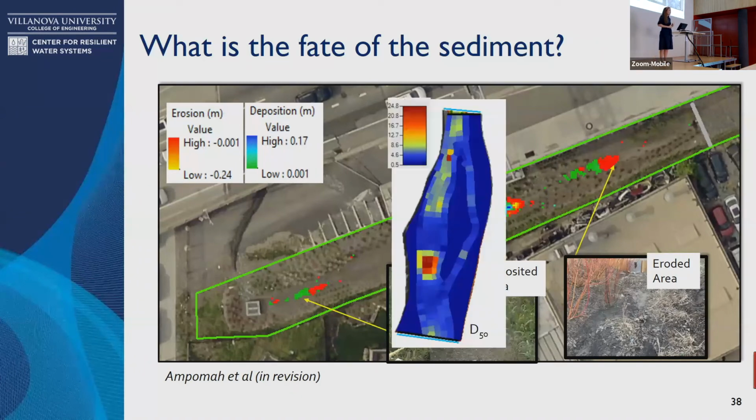So now we're trying to think more about the advection processes of sediment and fines as this is moving through the system. And once we understand where these fines are going, this is also going to allow us to understand more about the transport of pollutants into these systems. PAHs adhere to sediment, and they get transported through wet systems attached to sediment. And if we understand where this is being deposited, we can understand where some of those contaminants are.